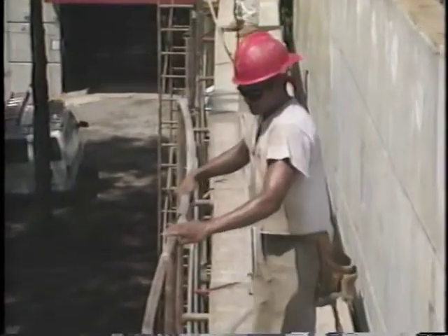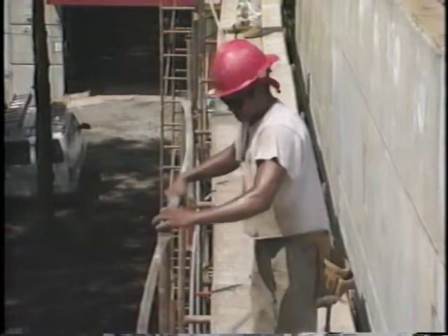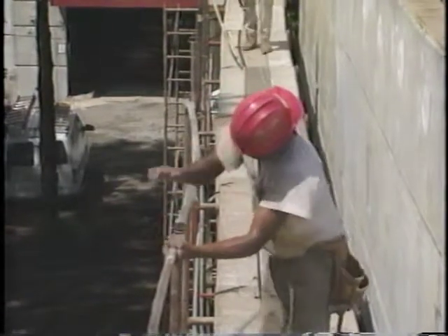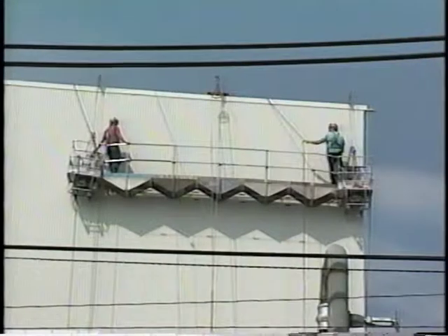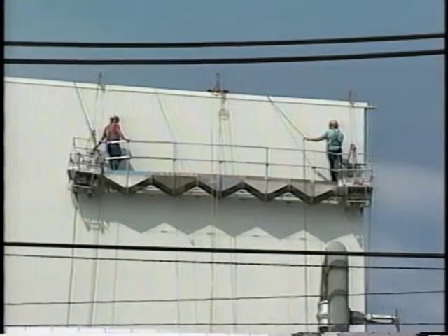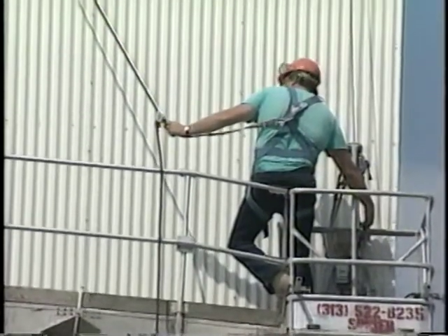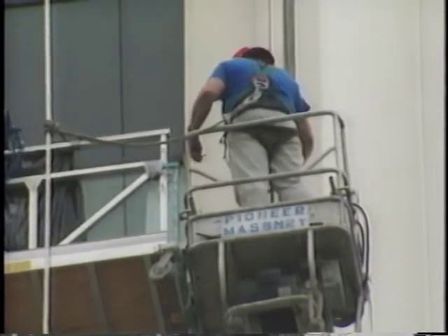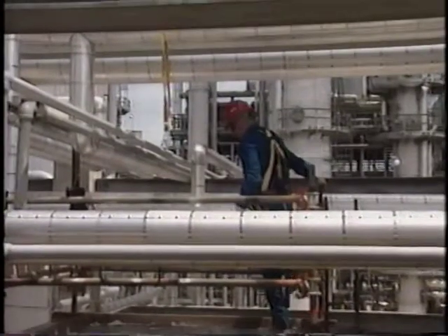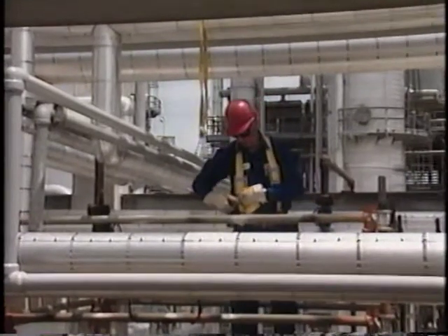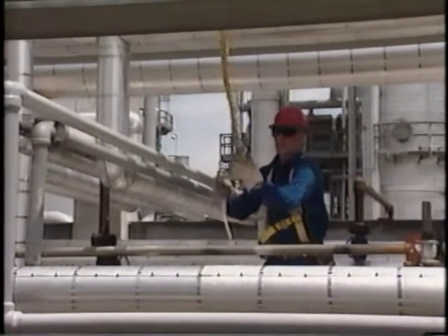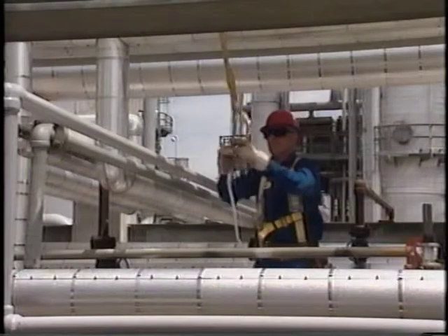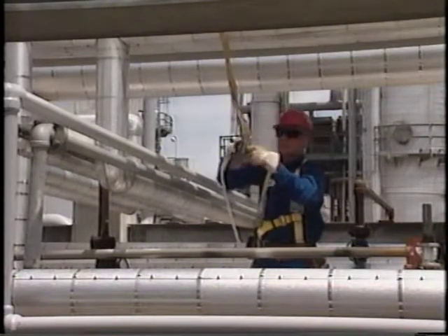Guardrails of at least 38 inches high on all open sides of the scaffold are the primary form of fall protection. When platforms are less than 18 inches wide, guardrails are less than 36 inches, or single or two-point suspension scaffolds are used, then the personal fall arrest systems must be used beginning at a height of 10 feet. A personal fall arrest system consists of three main components: a full body harness, a lanyard, and an anchor point.